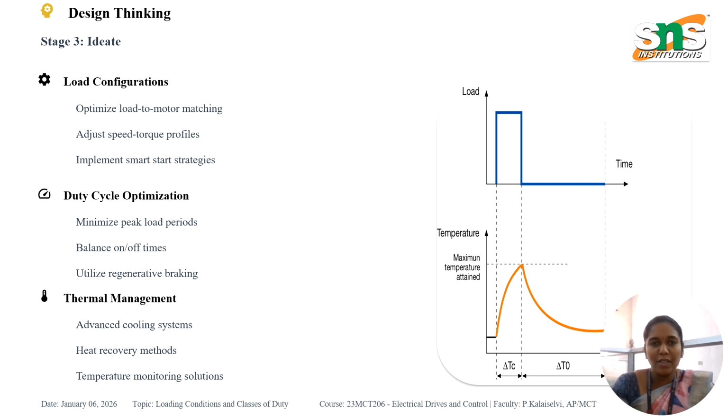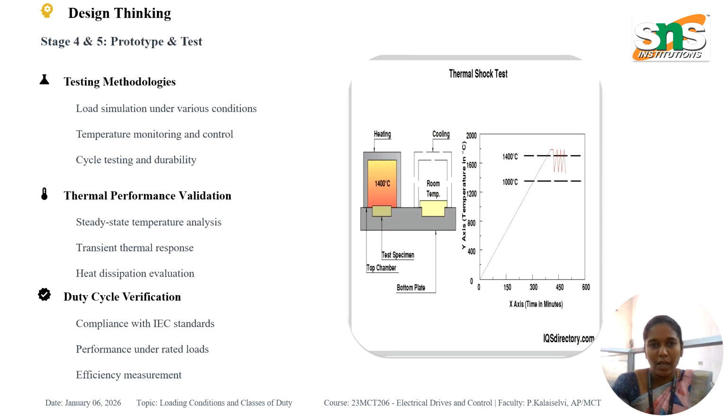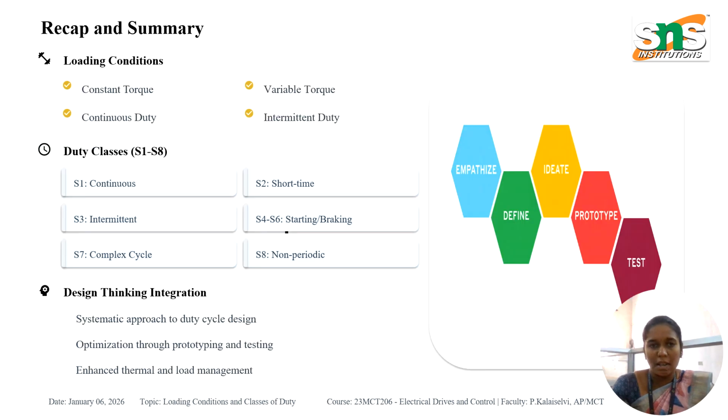After defining duty, we move on to the final stage, ideate and prototype testing. For ideate, we improve the speed-torque profiles, use smart starting methods and apply regenerative braking. For the testing operation, we perform load simulation, temperature monitoring, and cycle durability testing. Likewise, this ensures reliable drive designs.